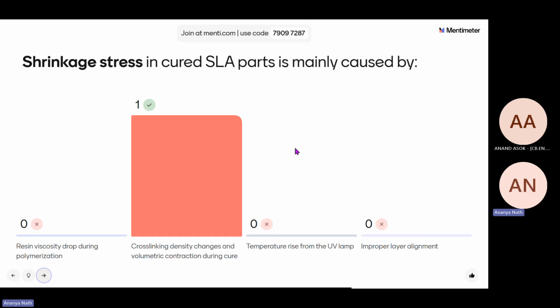If that combination is enough to cure 20 micron depth of resin, then you can choose the layer thickness as 20 micron. So if your power is 20 watt and 3 seconds of exposure time is enough, then your power is 20 watt. Now, if you're putting less than 20 watt, then that much depth will not be cured because that much heat is not coming. Laser power is directly proportional to the heat. Power is basically heat. So if we are putting less power, less than 20 watt, the curing depth will decrease. That much resin will not be cured.